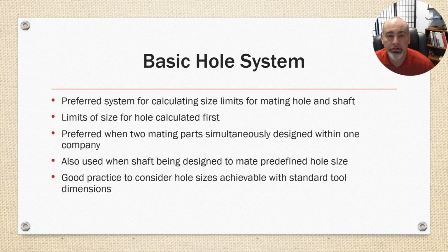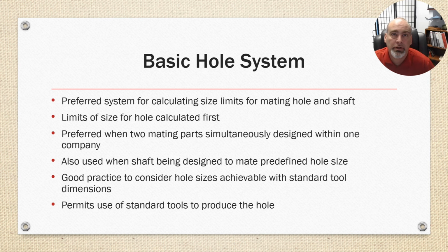There are standard drill sizes. And if you can make your tooling to standard drill sizes, and then make the shaft fit, you're not getting special tooling to make the holes. And it permits the use of standard tools to produce hole features.